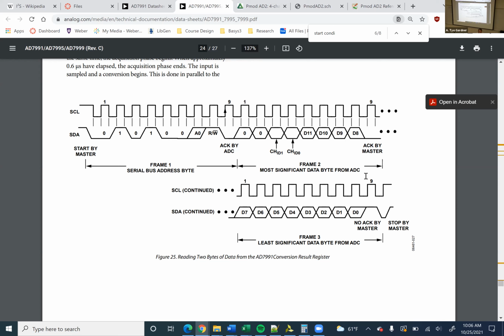Is the I2C clock just a regular clock, or is it kind of like a SPI clock? It's going to be high until activated, because you want it to be high for your start condition, right? So you're going to put it into a situation where it can be started. Your stop condition is kind of the same thing, which is going to be like a rising edge of clock while the clock is high, I think, but I want you guys to go read and verify that that works.